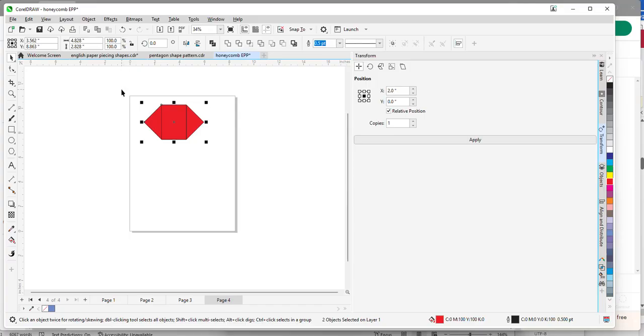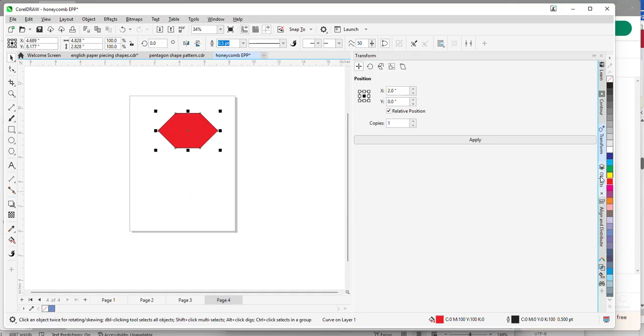Again, there's other menus. There's many ways to do this, but if you know the shortcuts, it makes everything a lot faster. So while they're still selected together, I can press the weld tool just like I did before, and now we have one solid shape here that we can duplicate and rotate and make patterns out of it, and they will all nest together.